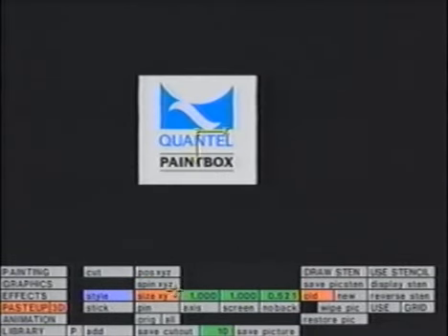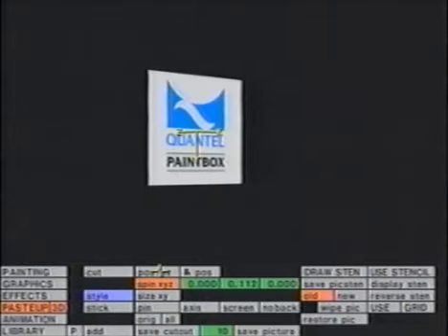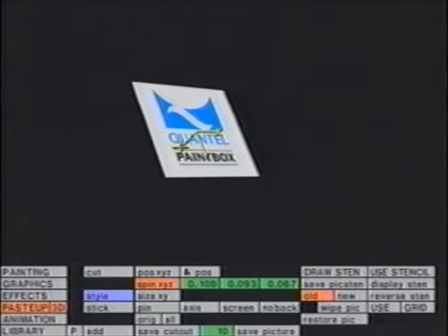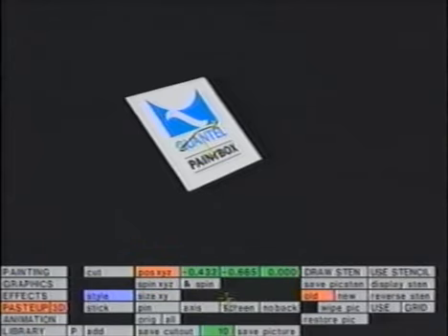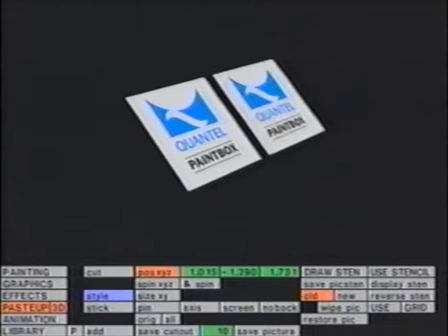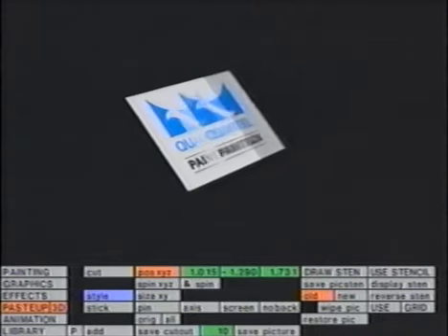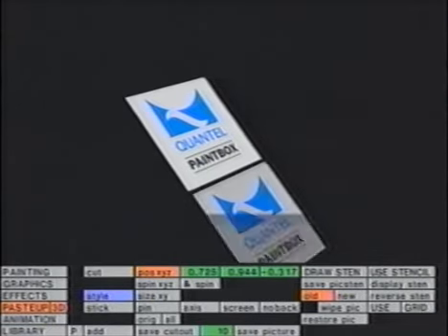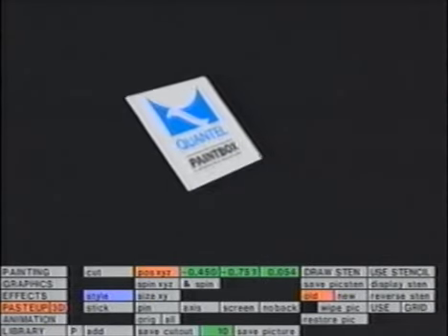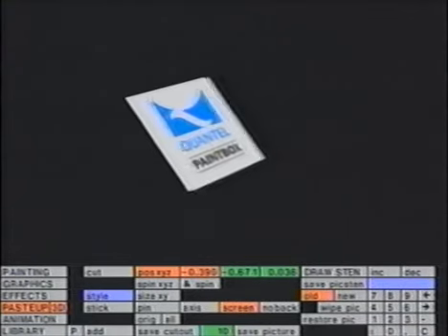Normally, all changes are referred to the cutout itself. Here, a cutout is stuck to show that subsequent moves on the X or Y axis are in the plane of the cutout. Using screen, all movement of the cutout is in the plane of the screen, not that of the cutout.